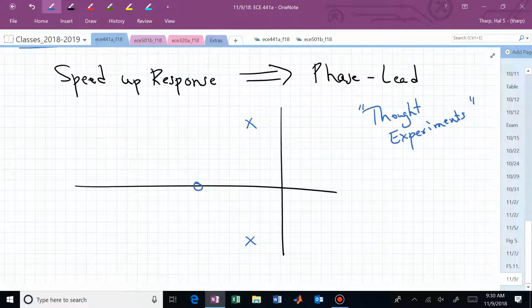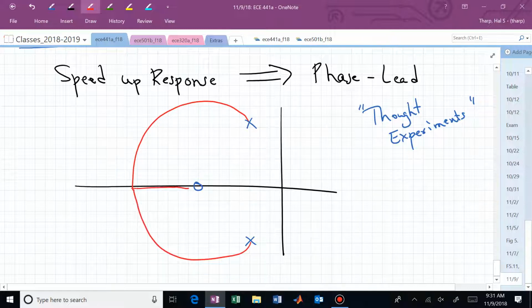What's the root locus look like for this configuration of poles and zeros? Two poles and a zero. Walk into it. Remember? This is now two poles to the right of a zero. You can pull out your compass and draw this. There's the radius, and the center is the zero. I won't be able to draw it, but you can use your imagination. That's what would happen. Does that move our root locus or change our root locus shape dramatically?